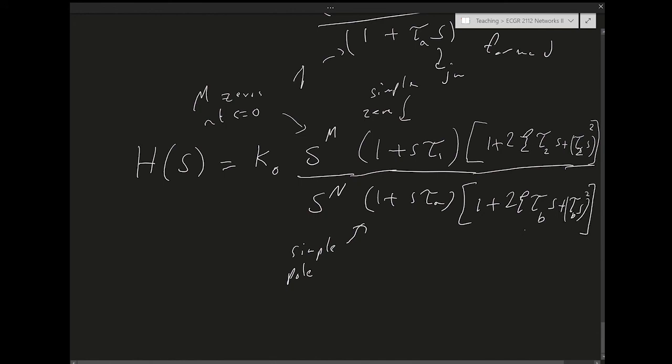This is very similar to what we did for second order systems. We're just taking the second order polynomial and defining the constant this way. It turns out that this constant zeta quantifies the damping of the system, how much the system is damped. Tau, by the way, is the time constant. It quantifies how fast or slow the system is, right?